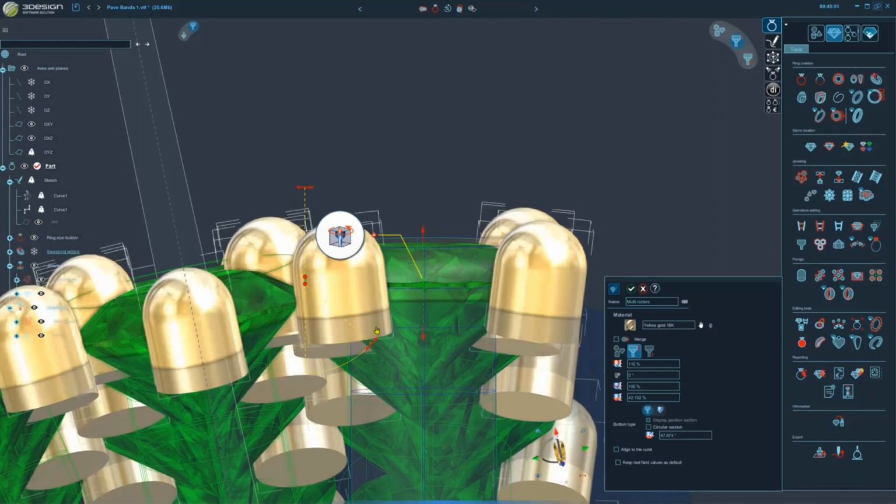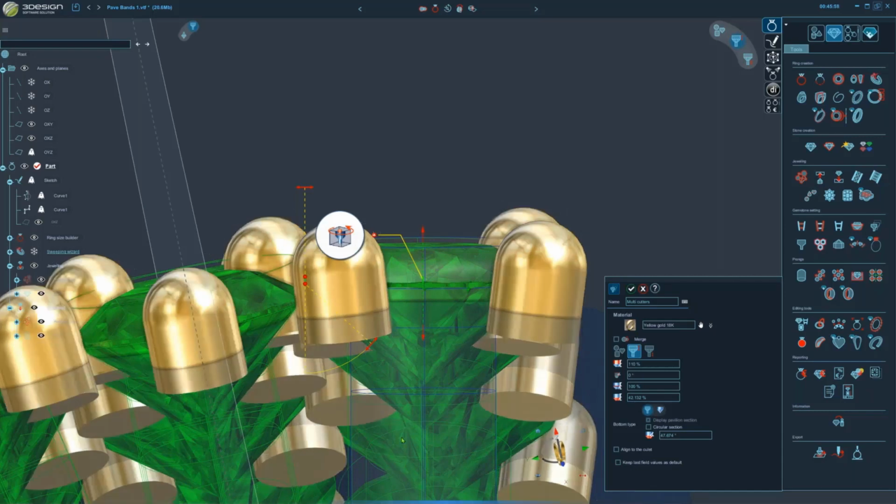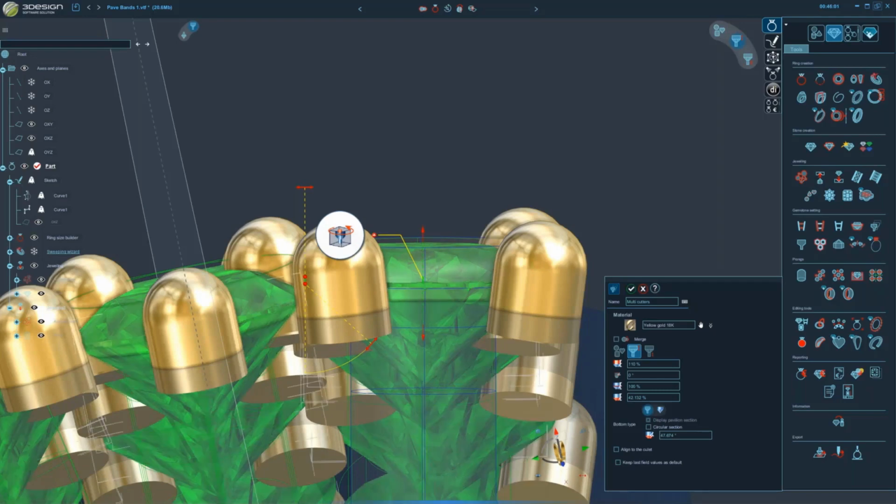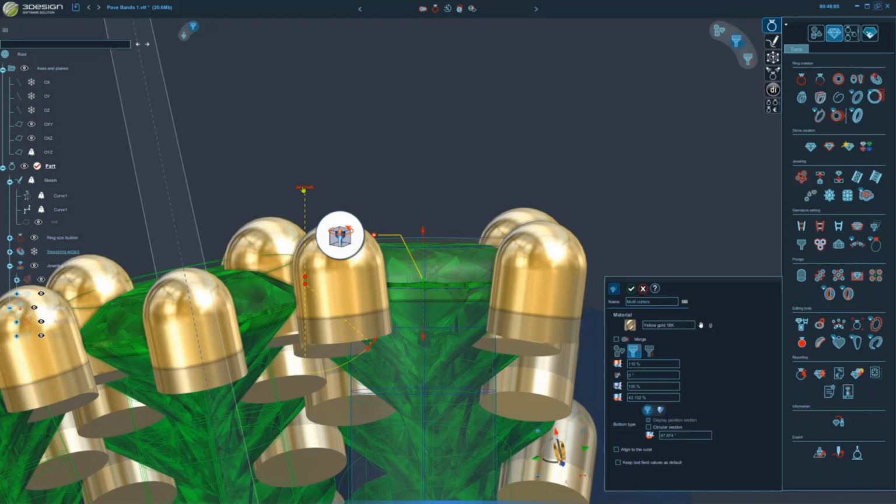So when I'm doing standard round cutters like this, I don't need to adjust the bottom shapes. I'm not going to do any fancy patterns on the opposite side. Those are the only two things you really have to adjust. The top height is plenty as long as it's outside of the surface of your ring. You don't need to bend over the top part here to create the angle cutter, since we're not going to be cutting into any claws or anything. So that's really all we have to do. Go ahead and validate that.